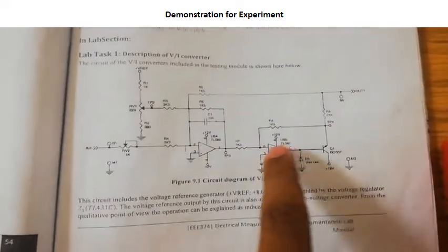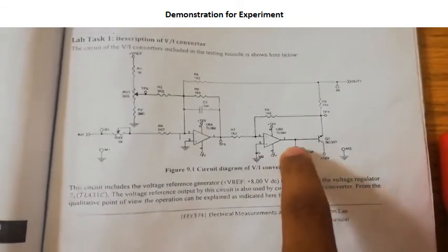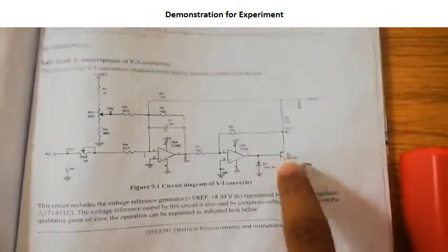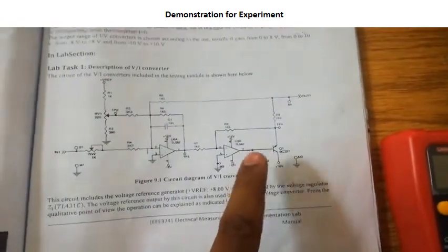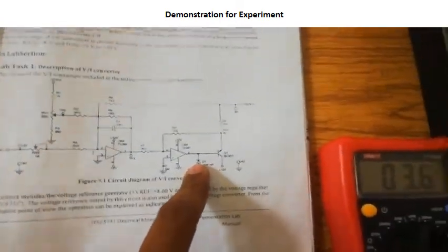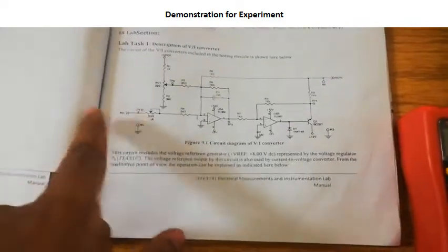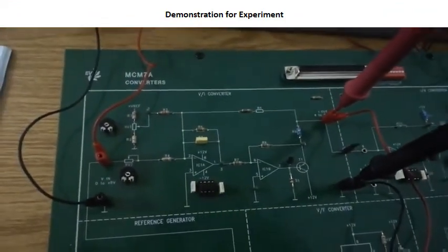This is the circuit diagram containing two amplifiers and one transistor and one Zener diode and a variable resistor. When we supply the voltage to the circuit, the variable resistance acts as a reference and voltage is amplified from the first amplifier, which is at the left corner of the circuit. And at the amplifier number 2 there is a Zener diode connected in reversed bias position, which will act as a regulator along with the second operational amplifier and give the signal to the base of the transistor at the end of the circuit.